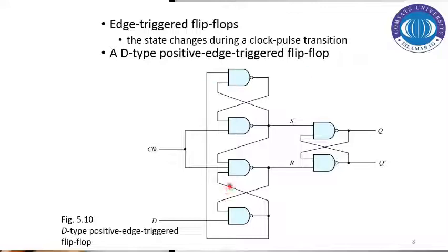But you can also implement that from scratch if you are not willing to instantiate or reuse your previous lab codes. So what you have to do is you have to make a module containing the description of a D flip-flop and implement this diagram, but you have to make sure to label the interconnections or to define the wires properly, because here you can see that there are a bunch of wires which you have to define in order to make interconnections between these gates.